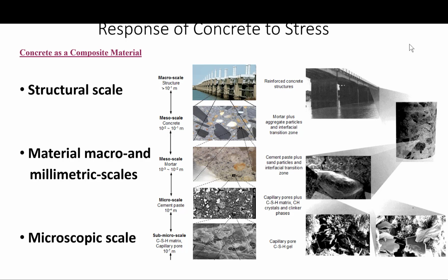This zone plays a role in the stiffness, strength, and permeability of cementitious materials containing aggregates due to its generally low density and decreased strength compared to that provided by the bulk cement paste. This is often referred to as the weak link in concrete. I will elaborate on this ITZ a bit later in this presentation.